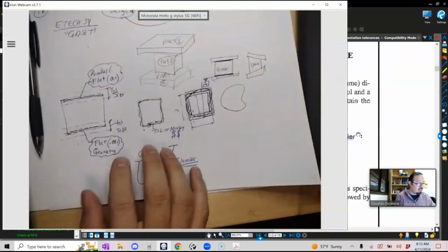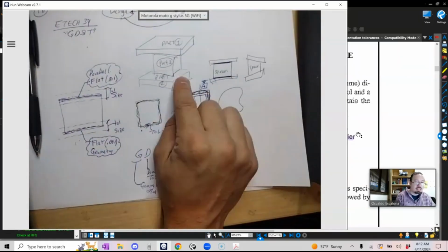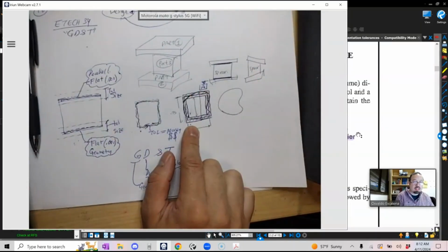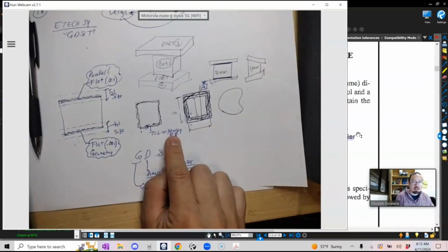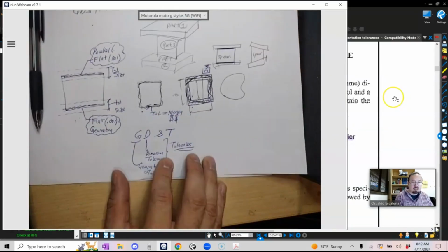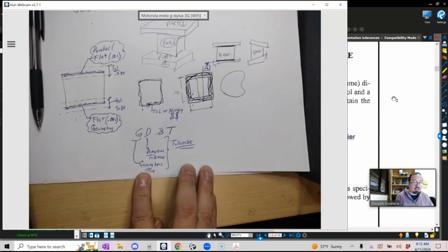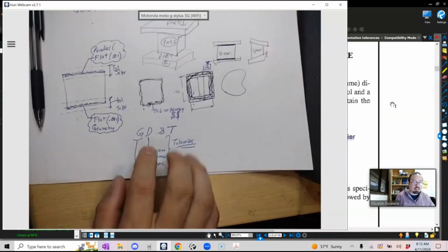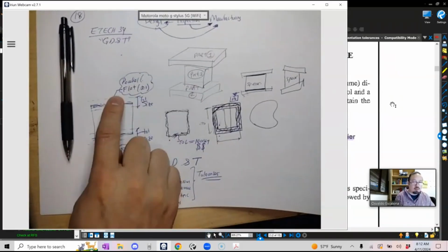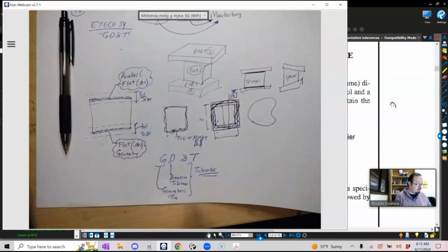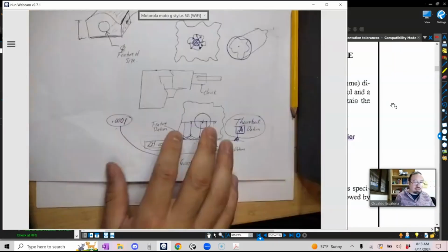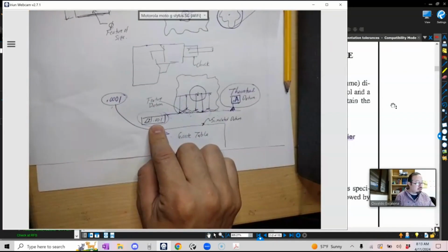The example that we did at the beginning of the class when I introduced you to GD&T is a part with a function. In this case, it's just as simple as a spacer. We talked about regular tolerances, and if I want to reduce the tolerance, it's just going to cost more money. So instead, I introduced you to the language, which has two components: the dimensional tolerances and the geometric tolerances. The geometric tolerances focus on the function itself, how flat I want it and how parallel I want it. We could put some notes, but instead we are going to use GD&T, which gives us the tools to put the language on the drawing.